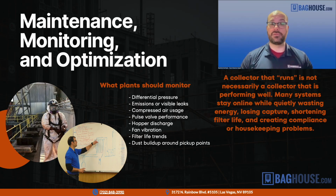Simply upgrading the gauge from a basic magnehelic gauge, which is just a mechanical gauge you look at, to one that has a 4-20 output will allow all of those readings, especially those far-flung bin vents on the top of the silos that take 20 minutes to get to and up a 150-foot ladder, to be sent down to the control room via 4-20. For the extra $50, $80 it costs, it was an incredibly wise investment. So make sure those are monitored at all times. It's also easy to access, and reduces a lot of unnecessary labor.